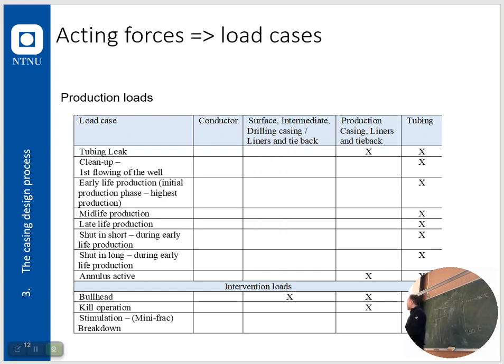Active annulus, that's the gas injection. Bullheading, that's killing. You consider wellhead fatigue with this, like if you shut the well in and you release and you shut it in. No. So we don't do wellhead fatigue as part of that in the casing design. Wellhead fatigue, to my understanding, and that's what I have to answer you, it's a very good question. I have never considered it. That's my answer to you. Some may do actually, but I don't think so.